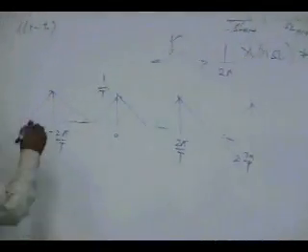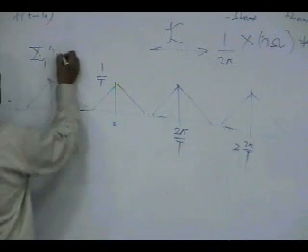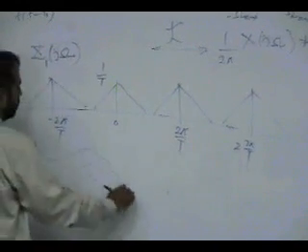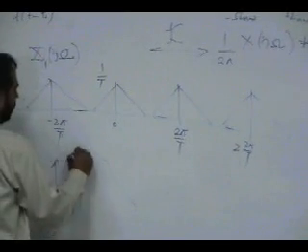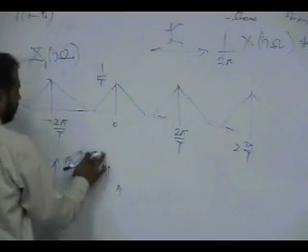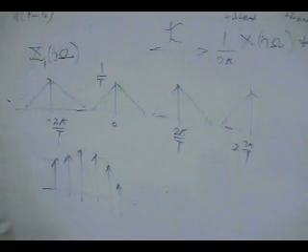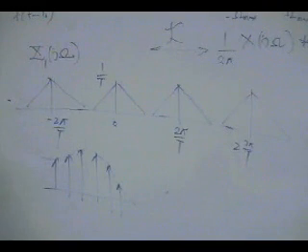This is the Fourier transform of the analog signal xi(jω). This is the signal where we were saying you have only impulses, right? Then we said in time domain you divide the axis by capital T to make it digital. Here you need to multiply the axis by capital T. You do the reverse to make it digital.